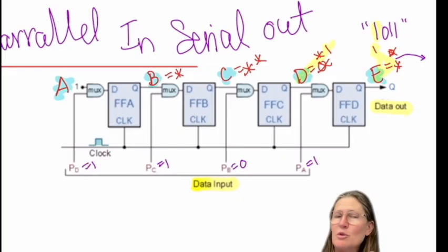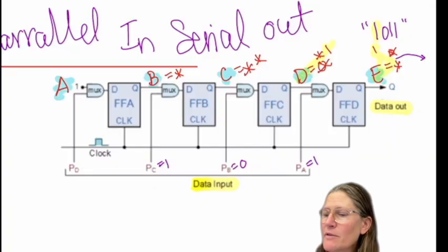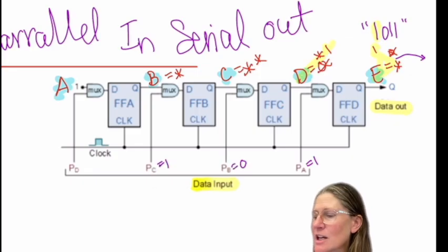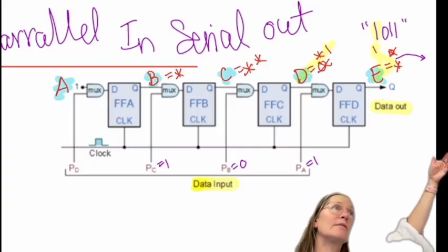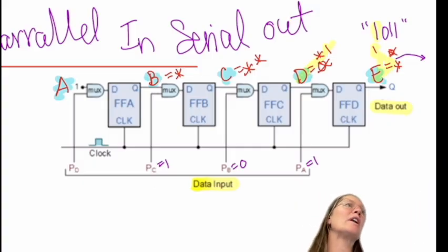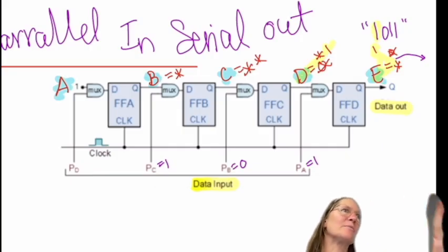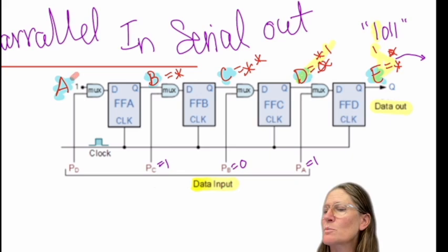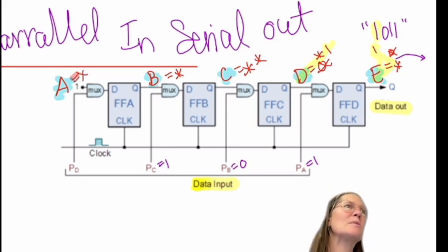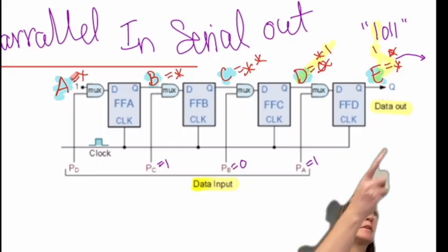So when you actually do this, you put the values 1, 1, 0, 1 on there, and then you take them off after. What the MUX does is it senses that you don't have data on this line anymore, and then it's going to read whatever A was. You don't know what A is because it's shifting in from something else too. So it will be something, but it will be kind of an X because it could be a 1 or 0, which doesn't really mean anything.